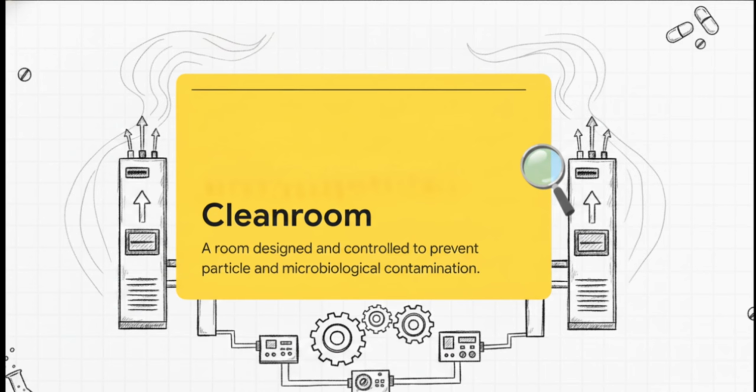By definition, a cleanroom is a room designed, maintained, and controlled to prevent particle and microbiological contamination of drug products. And because oral solid dosage manufacturing involves highly active powders and, let's face it, very dust-generating processes, a cleanroom isn't just a tidy space. You can't just mop the floor and call it a day, right? It's a rigorously assigned, mechanically reproducible environment where literally every cubic inch of air is actively managed.